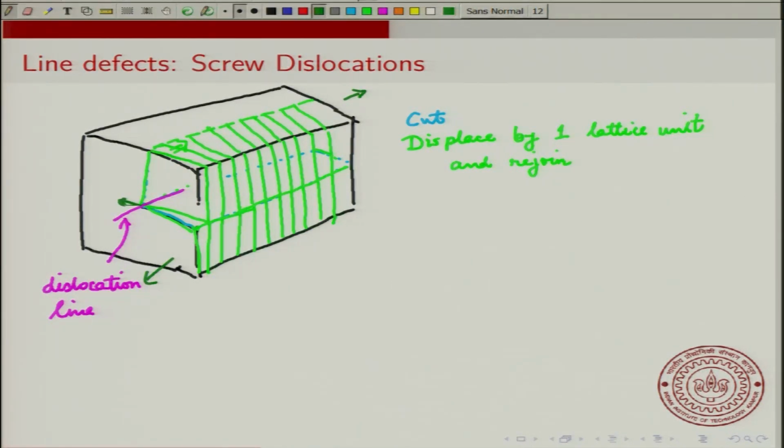So you really have to imagine that when you take this dislocation and start shearing it, the direction of slip and the direction of motion will be this way. So instead of joining here, it will join here. And you can imagine that you will get a longer curved line. So the screw dislocation is another kind of dislocation.